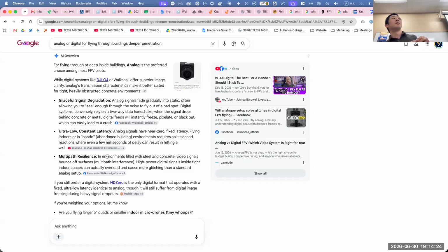Are you overriding what the VTX allows? Well, on your Betaflight, you can do a lot. Yeah, that could be for anything, right? Like if you go beyond the rated limit. The VTX is the hottest thing on your drone. So later when we start working on it, we need to use our old vents or solder fume extractors to keep it cool.